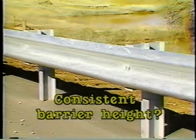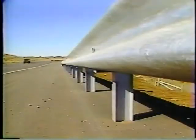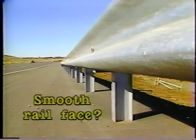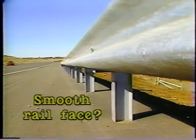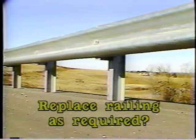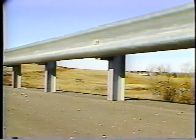A range from 24 to 30 inches to the top of the rail is a common requirement. Is the rail face smooth? Are splices lapped in the direction of traffic flow? Are post connections properly installed and tight? And finally, do the rails, support posts, or other elements show any signs of corrosion or damage? If so, have you taken corrective actions?